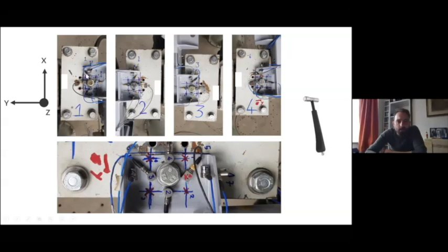And you can see that there's multiple accelerometers attached. Here there are 1, 2, 3, 4 pointing in the vertical Z direction. There's 1 pointing in the X direction, and there are further 2 pointing, not so clear on that figure, in the Y direction. If you look at the close-up at the bottom, 5 and 6 accelerometers are pointing in Y, 1, 2, 3, and 4 are pointing in Z, and number 7 is pointing in the X direction, but it's just oriented slightly different.